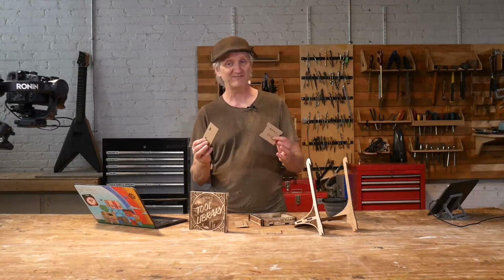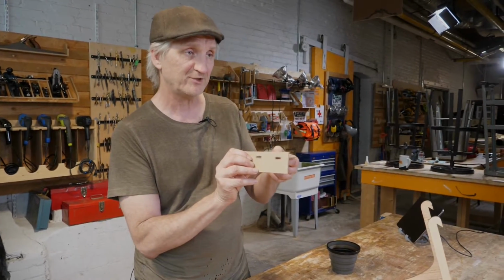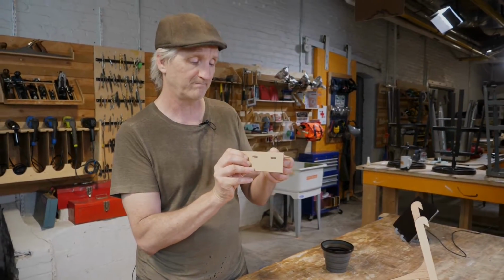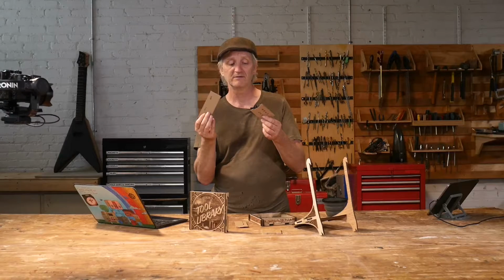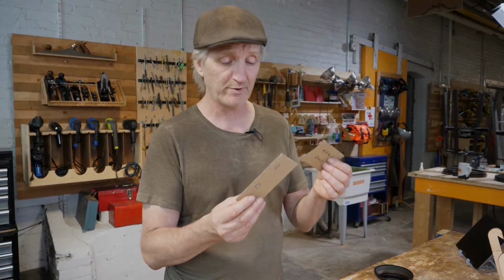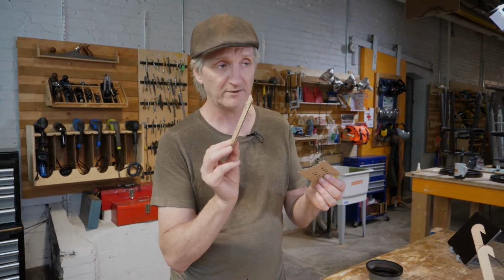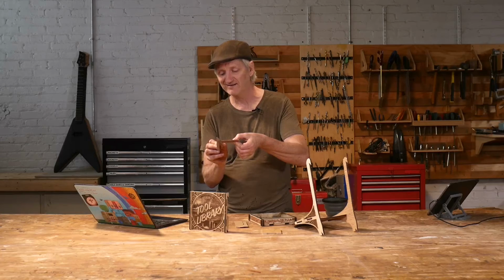So have you got the idea? Having multiple bodies allows us to move a bunch of features using a transform. But if we want to reference geometry from one body inside of another body, well, we're going to have to use a tool that's called the Subshape Binder. Now we're going to be using that to perfectly position the slots in one body using the tabs in our first body.